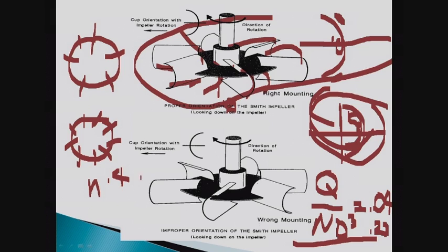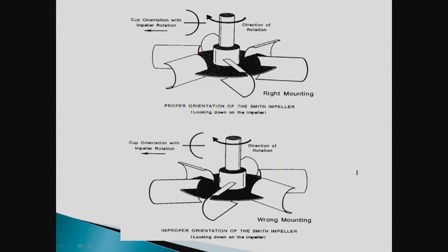Okay. So anyway, get up here and erase all this. Now then, it's very easy to have these blades flipped. Your maintenance people or the people installing this impeller, you tell them to mount it like this. And I've told this story earlier, I think. Sorry, a little bit of repeat. They'll look and say, this just doesn't look right. It's not hydrodynamic. They'll turn it around and mount it like this.